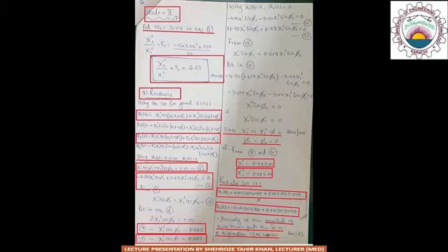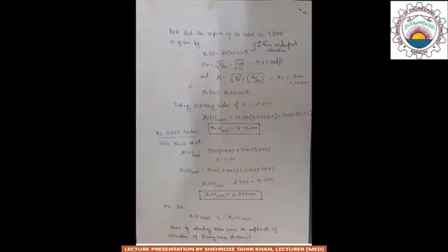In the last, we have some more numerical calculations in order to prove that by attaching the secondary mass to a primary mass, the vibrations of the primary mass can be controlled. So let's consider the optical table as a single degree of freedom system, and we know that for a single degree of freedom system, the response of the system is given by x1 of t is equal to A cos omega n t, where omega n is the natural frequency, which is given by under root k upon m.